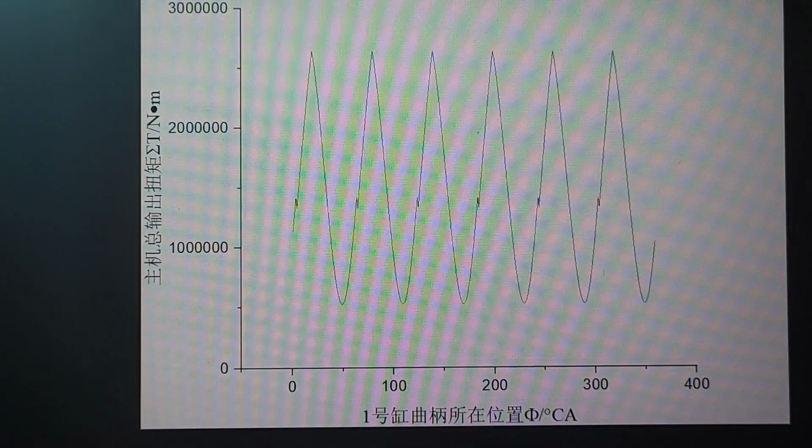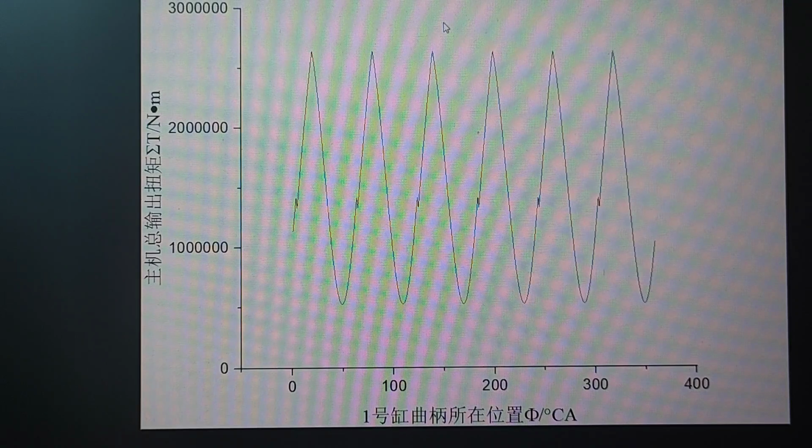And I remember the next thing is the composed torque of the whole engine. This is quite simple since we just need to add up all the single cylinder torques, and you know that it must follow the firing order.